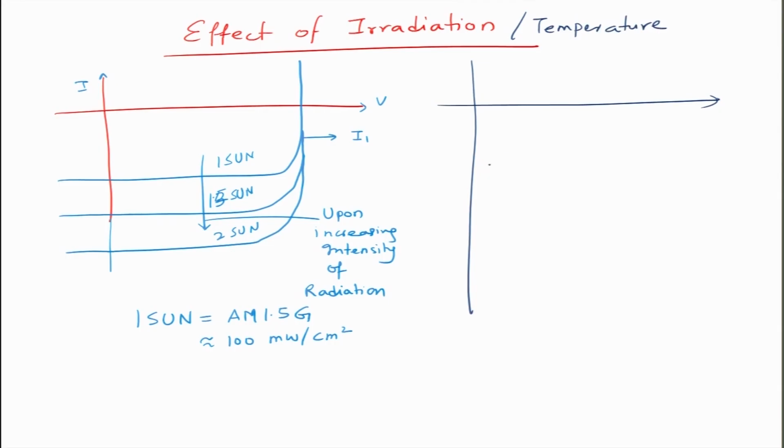So, this is increasing intensity. If I make a plot for this, for example, this is for the first temperature T1, and if you go to a high temperature, the high temperature leads to more emission, but it also reduces the VOC. So, as a result, high temperature will result in a reduction in the VOC, generally like this.